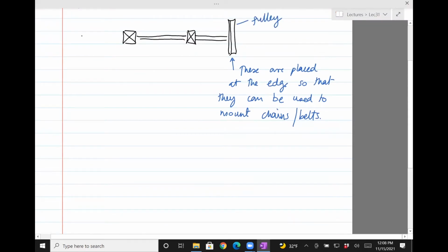Okay, some other things. Avoid long shafts. Clearly, as the shaft size grows, and they're simply supported, you'll see that deflections also increase. For the same load, you'll have a bigger moment, and so you want to avoid those things. So avoid long shafts, or rather, let me just put it this way: keep shafts small, keep shafts short, ideally on two bearings.